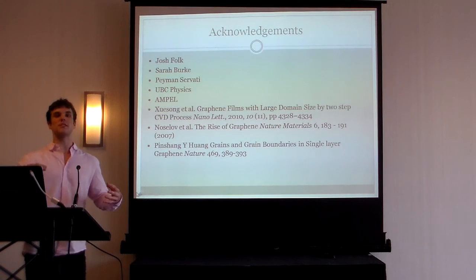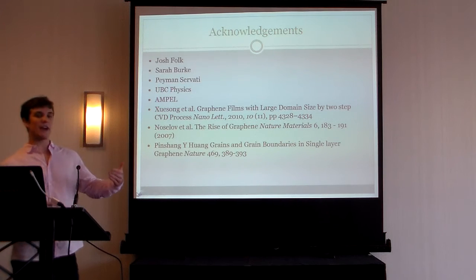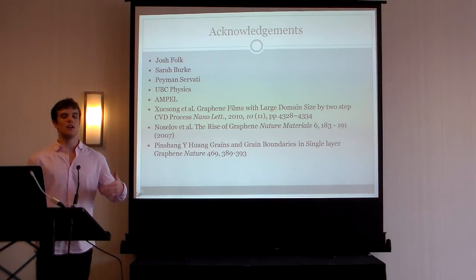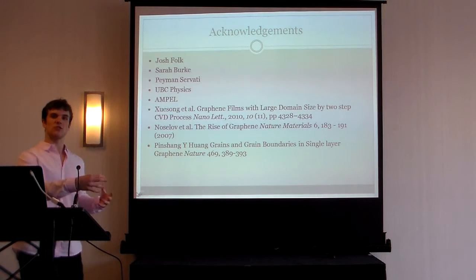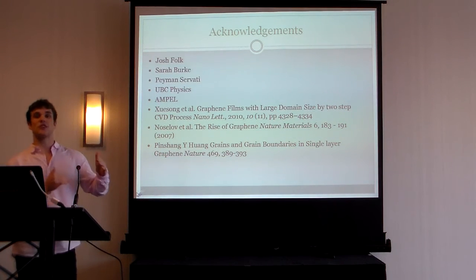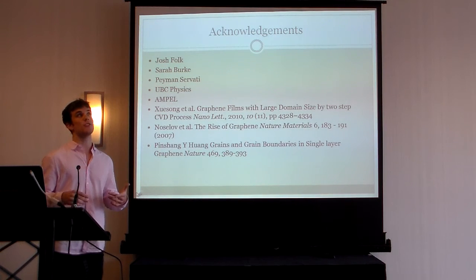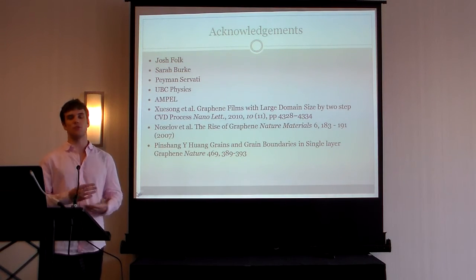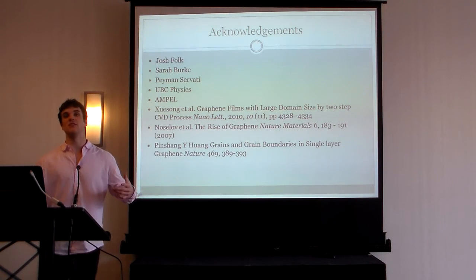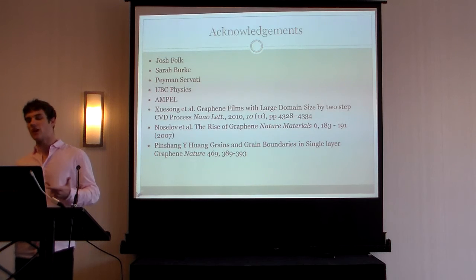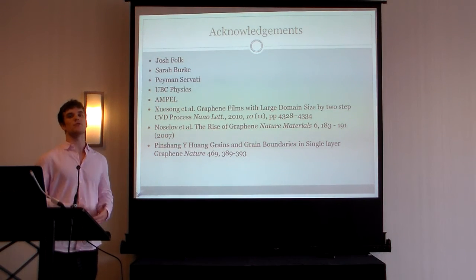They have six-fold symmetry, but they look like dendrites growing. The more hydrogen you have, the more you etch off the less favorable growth directions, and you get more sharply edged hexagons. More hydrogen has been found to create better quality films, but the growth time has to be greatly extended for them to be completely continuous. So it's a toss-up between continuity and quality, and that depends on your application.